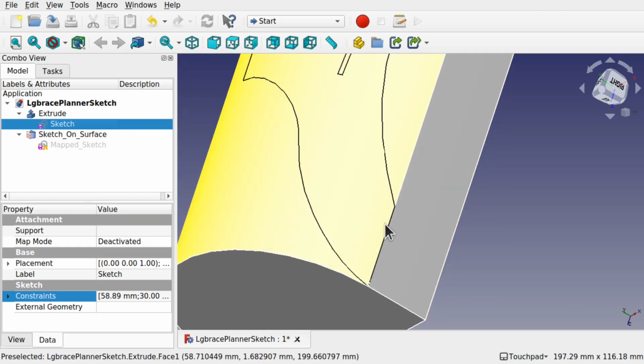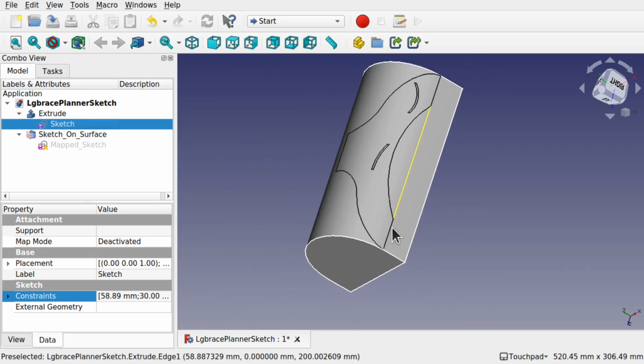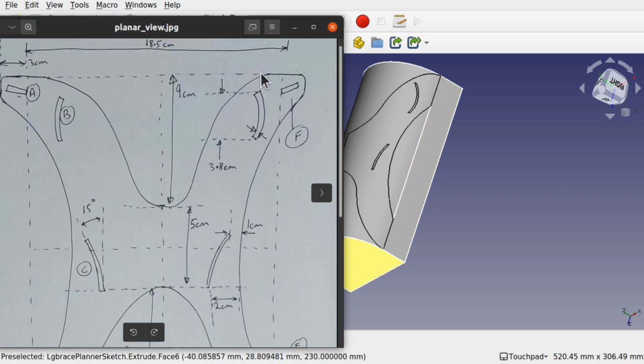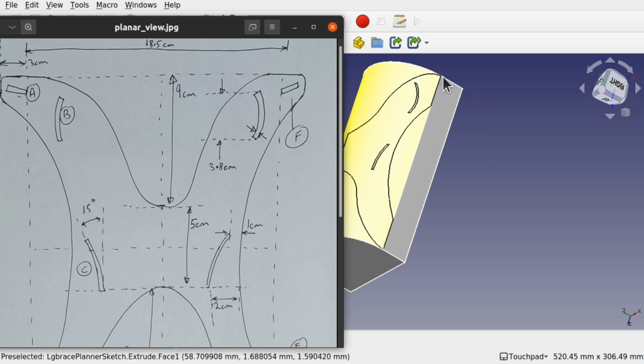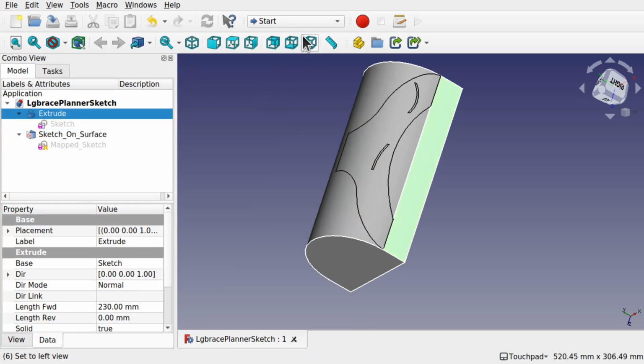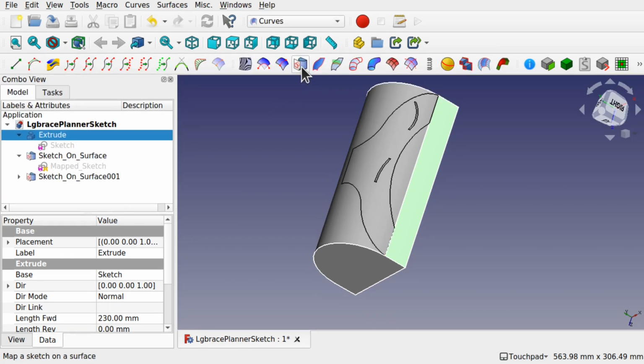Now looking, yeah, I've got a line there, that's good. Now we've got to follow this onto here. So we need the curvature that comes down here. I am looking at this up here because this comes down straight. So I put a straight line in here. We go down and we curve around. So let's add a face. Sorry, sketch on that face there. So sketch on the curve surface. That's added that sketch on there.